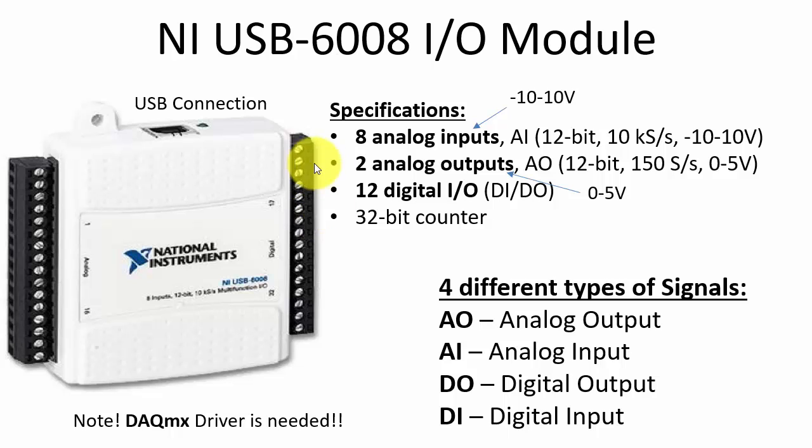Here you see an overview of the USB-6008 I/O module. Here we have the connection for the USB cable. So after you have installed LabVIEW and the DAQmx driver, you can connect the device with your PC, and then the device should be ready to use. Here you have analog inputs and outputs, and here you have the digital inputs and outputs.